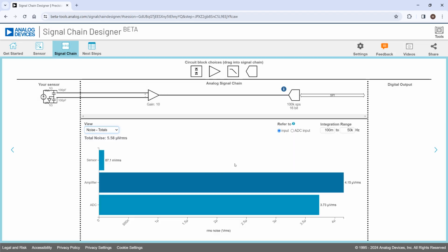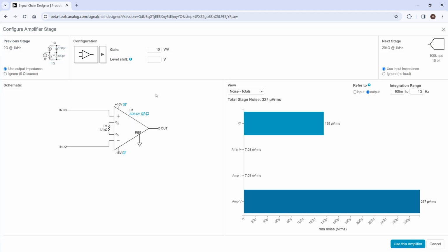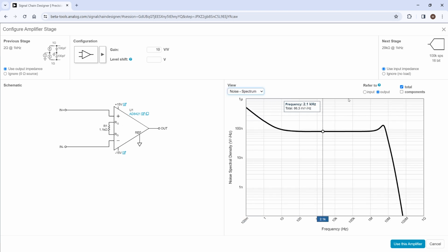And so with the integrated noise at the signal chain level, I am integrating that 18.6 value across all of here, versus at the stage level, I am only integrating that 8.6. So if we had no filter, so that the entirety of all of this noise graph got aliased, then we would get the same answer.